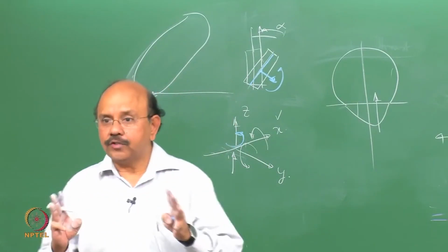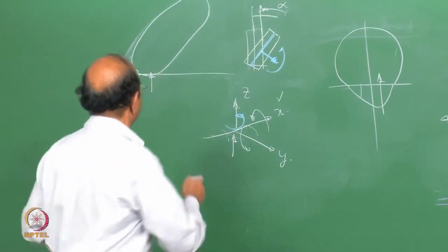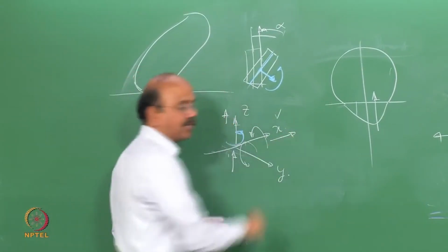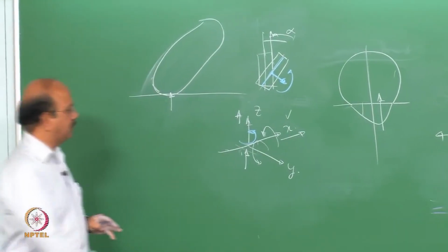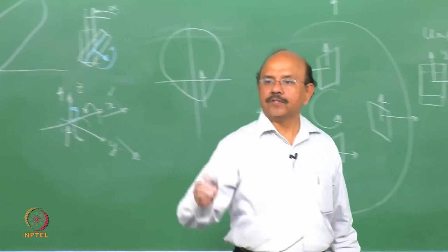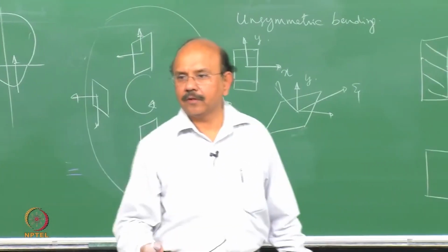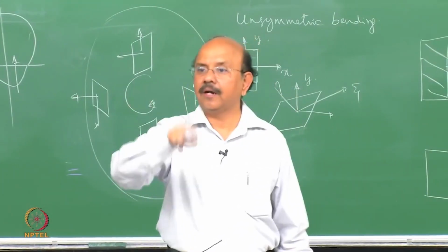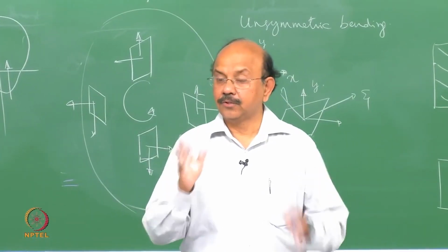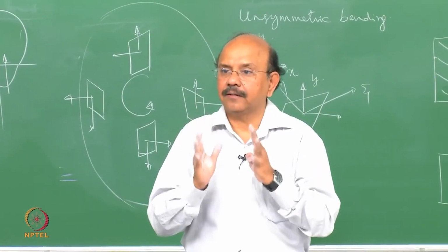So there are three forces: the normal force, the longitudinal force which gives the traction or braking, and the lateral force which is the centripetal force. Along with it, there are three moments. These forces produce moments in other directions. That's what we saw now. Clear? So it is not symmetric.